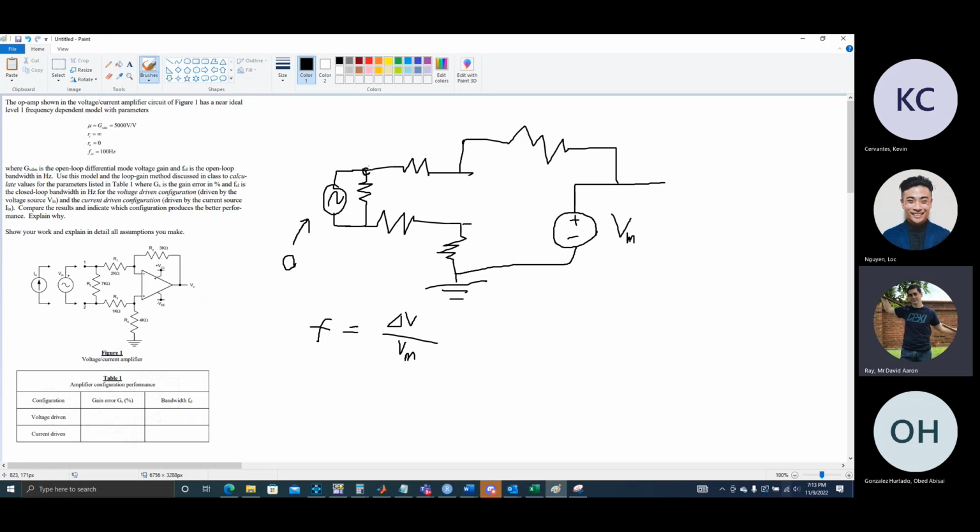So now it's saying the difference between this point and this point is 0. We know that current equals voltage over resistance. Since it's 0 over R, that means there's zero current, meaning there's nothing flowing through here. So we can pretty much cut this part off. Oh no, that's true. One second.